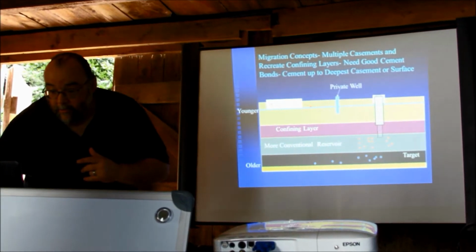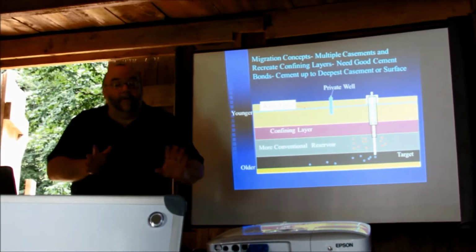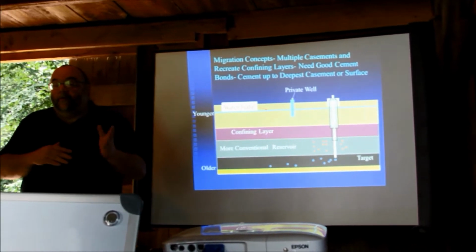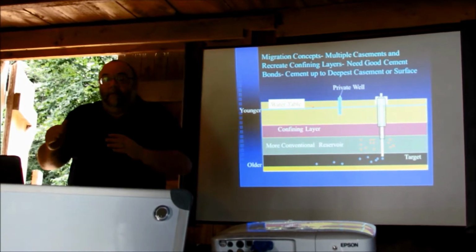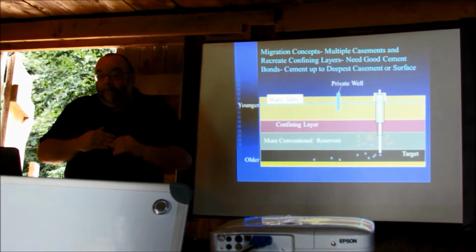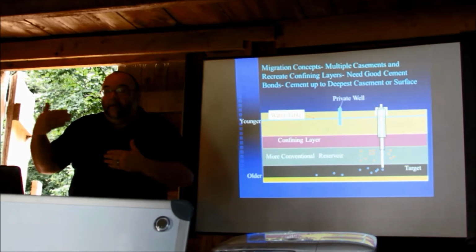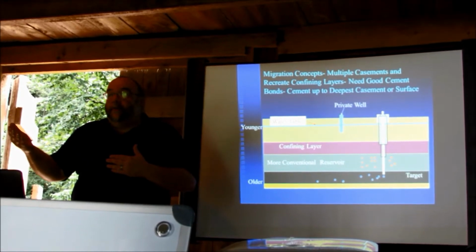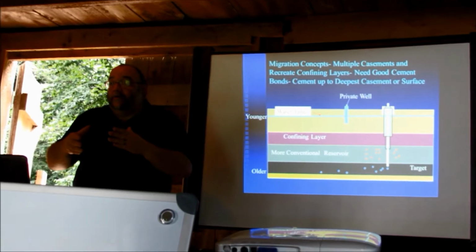Then when you call a shallow well, what do you define as a shallow well? Typically, it varies by region, typically 1 to 200 feet, maybe 300 at most. So anything under 300 feet might be considered a shallow well? Yes, but it does depend on place. You're also in a valley structure. So in a valley structure here, you might drill down only 200 feet, 300 feet, and hit saline water.